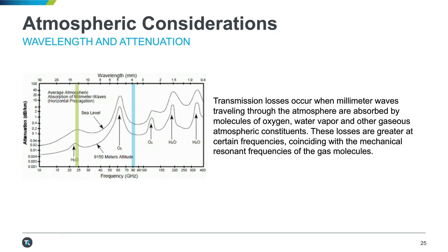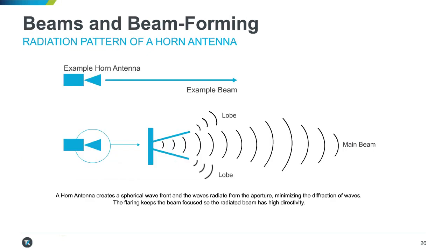Next consideration is the antenna pattern itself. Are we creating an accurate representation of the antenna pattern that we transmitted? So an antenna pattern is usually, and I used a horn antenna here, an approximation to a horn antenna's antenna pattern. So we have a main beam, and then we have a number of side lobes. Sometimes you have back lobes as well.